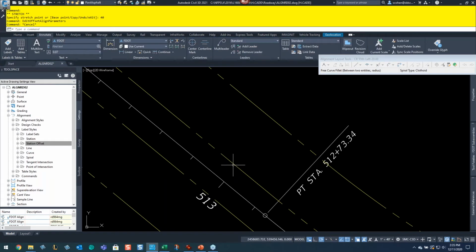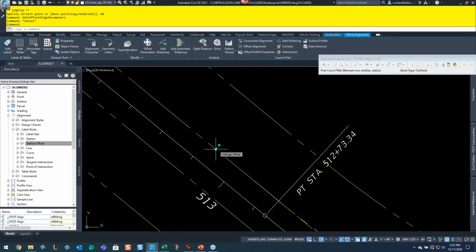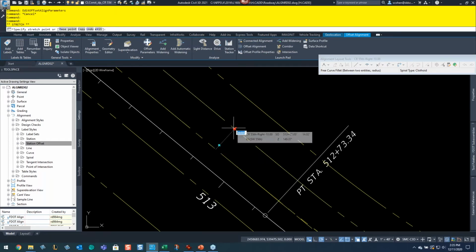Now for this one here, I do want one for the lanes eventually. If I was doing intersection design, you definitely want to do that. But for this one here, I need to do my clear zone. So if it's 29 feet, that's 12. That's 17 feet, right? Actually, no, it needs to be from the center line. My bad. So this is just 29.